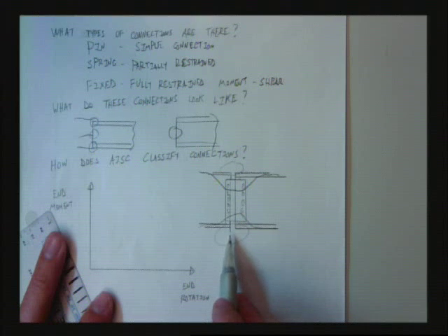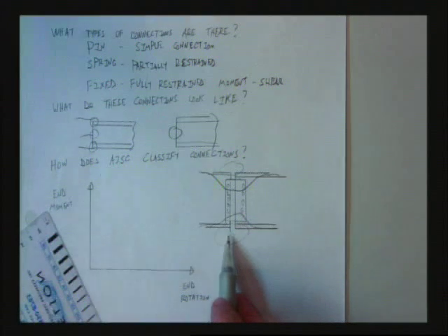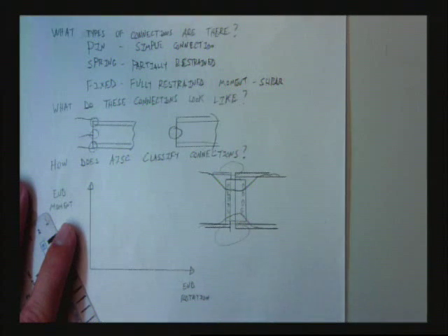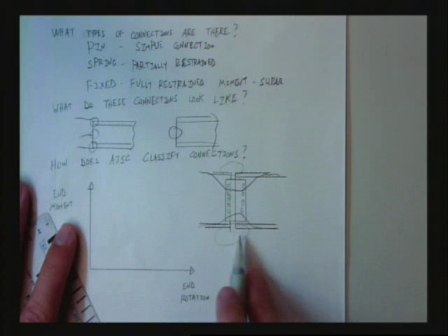Awesome. Now, telling you, if my PE is on the line, if it's something that I care about, and I'm not involved, like I don't get extra money because I save someone money, I'm going to assume it's a pin every day of the week. Okay? But design build is the future. Design build means the same group that designs it is the same group that builds it. And there's a huge interest then to save money on these type of connections and take more risk, more calculated risks. Does that make sense to everybody?